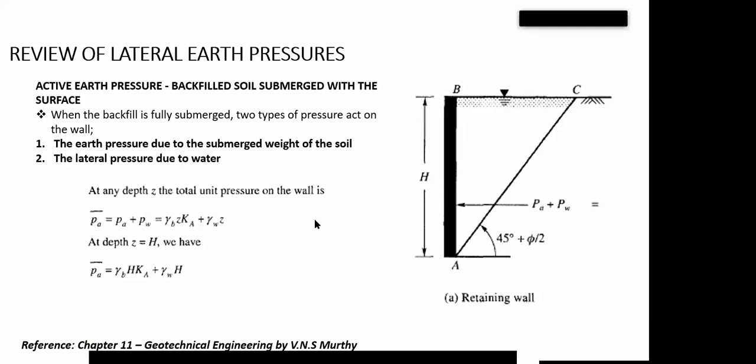Just like the way we derived vertical pressure, the way to derive the lateral earth pressure of water is basically to multiply the unit weight of water with the level of water. Once I multiply my unit weight of water with the level of water, I will get the lateral pressure caused by that water. In this particular scenario, we are not having anything like K naught or K, because it is water. You convert your unit weight of water to pressure by just multiplying by your height.